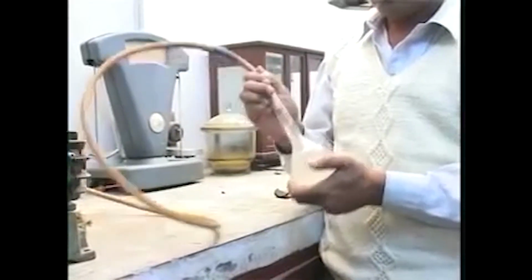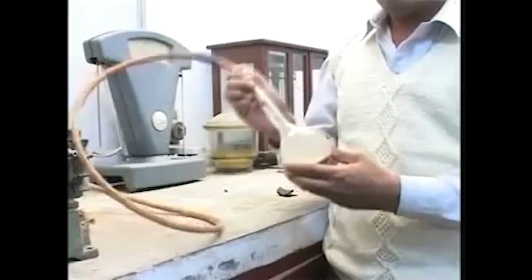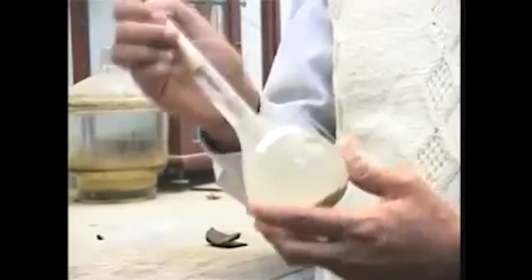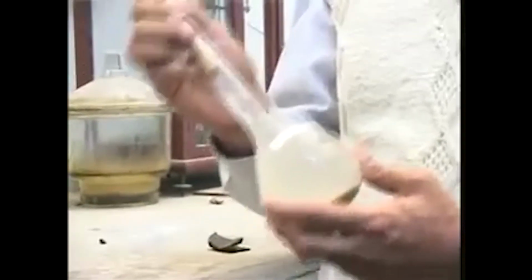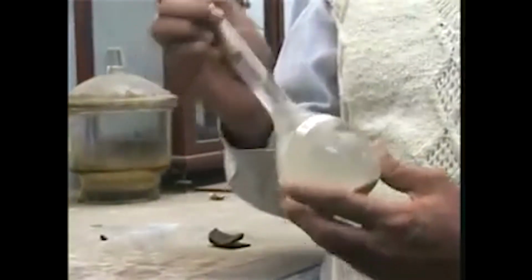Okay, so here you see that the soil is kept under a vacuum pump, kept under vacuum here, and that is being shaken by my colleague here, so that the mixture doesn't have any intrusion of air, because that might, as I was mentioning, introduce some error in the estimated specific gravity of solids.